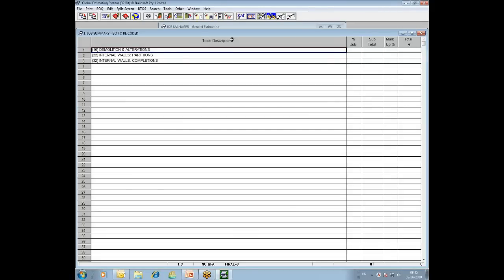What I'd first like to look at is what code files are used for. Code files allow you to resource a bill or a tender document into specific sections or groupings of your own making. They have a number of uses, one of which we're having a look at this morning, which is resourcing this bill of quantities into trade packages for pricing by subcontractors.